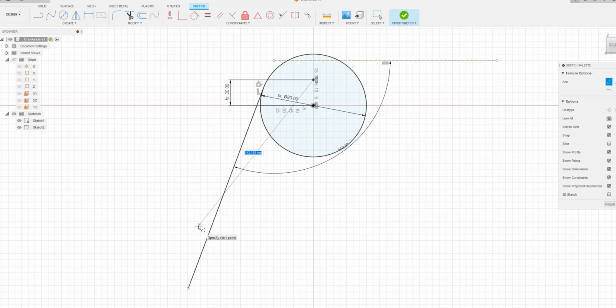I want to calculate it using the parameters already defined, and that is equal to the crank radius times 15/4. I know that that will give me a distance of 150. So with that, then I want it to end somewhere in the middle there.